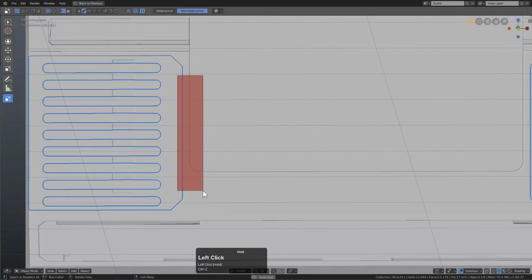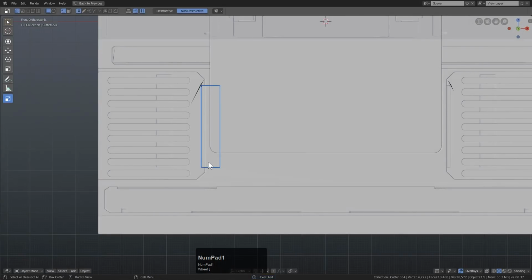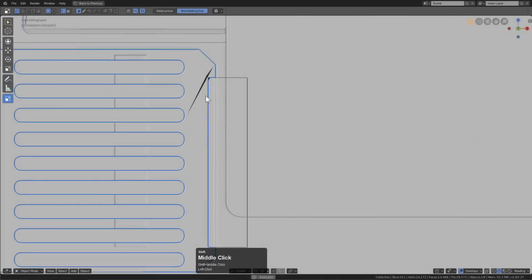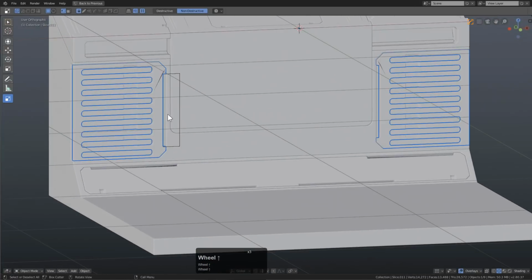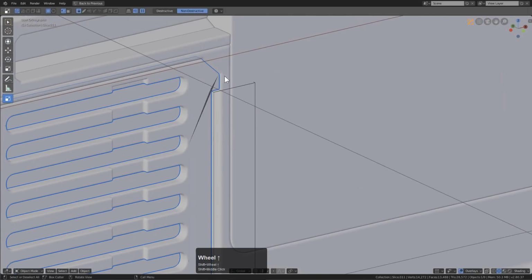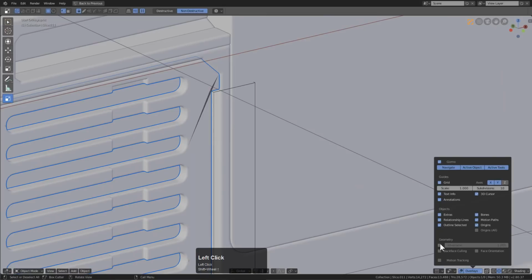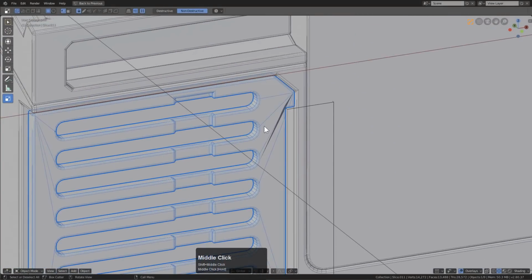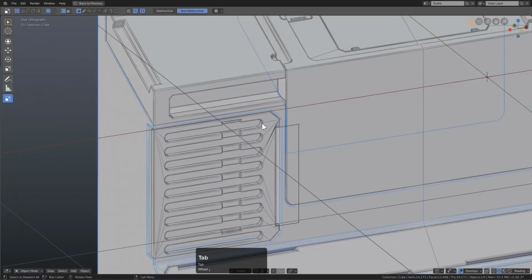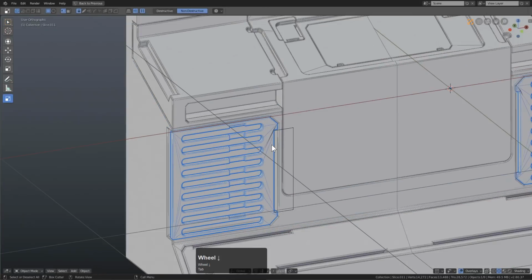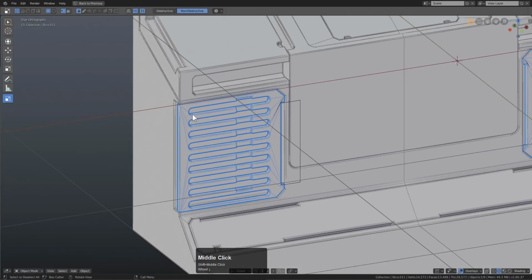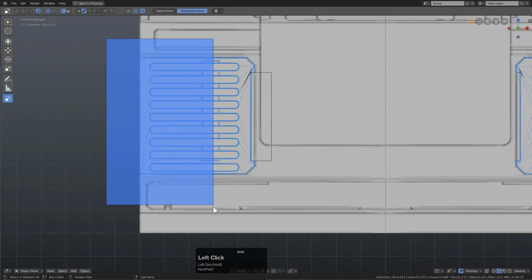Just don't see it. So bringing in these shapes, we can see that things are getting unruly with the boolean, with the bevel. And we can get in here and really look at this. So right here, I'm just going to turn on overlays. Let's look at what we have. Tab into edit mode. That's what we have. What if you could fix that with one slice? Blue box. Your time has come.